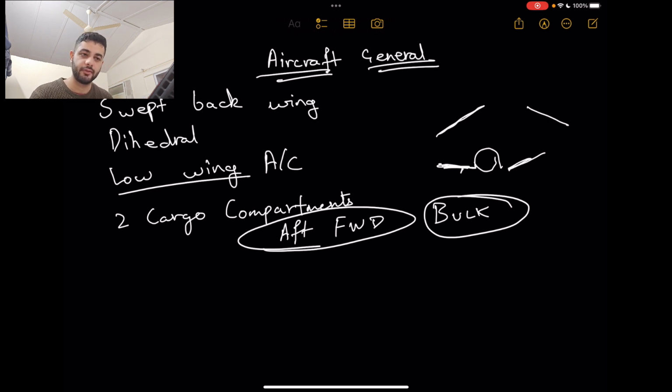You can also depressurize the aircraft through the avionics, but it's going to take time because the avionics has a very small hole to depressurize through, whereas the cargo door is a big huge thing, and it's hydraulically actuated. You don't need anybody right next to the cargo compartments. Anyways, we'll come to that chapter later. And then a few things about speed, range, basic stuff about the aircraft, how many pilots are required, all those. So this was what the aircraft looks like from outside. Now, the 320 is subsonic, medium ranged.